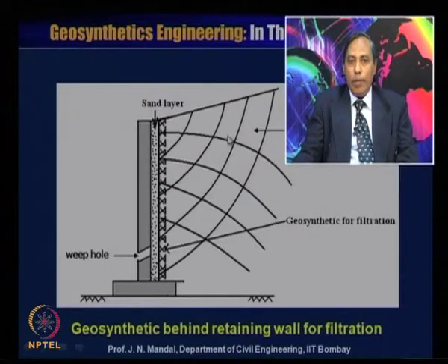The water can pass through the geotextile material and then the sand, then through the weep hole the water can drain out. So, here it has been shown how the geosynthetics has been used behind the retaining wall, and we will explain later how to design that. In this way you can also reduce the hydrostatic pressure here.